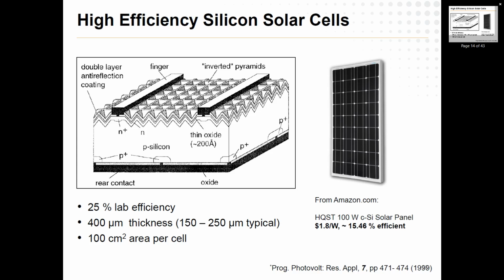So immediately you're losing a little bit of energy to reflection off those contacts. So that'll take off a few percent. You have this anti-reflection coating with your surface texturing here, and you try to capture all that energy. Some of it's just going to bounce off of there too. So there's some optical considerations you have to consider. And every time you create an electron-hole pair, maybe they'll recombine, or maybe they'll get to the contacts, or maybe they won't. So you lose a little bit there. And so that's why you can't actually hit the 32% in practice. You hit all these little roadblocks.